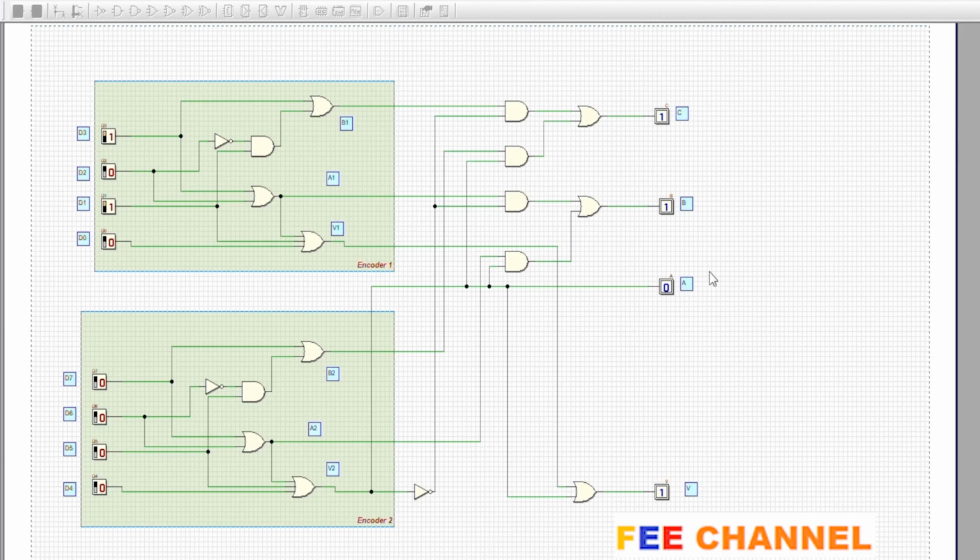But you can also use some directly available encoder ICs. For example, this IC 74148 is also an 8-to-3 priority encoder. And it can be directly used for some applications. But this IC has active low inputs and outputs. So while using this IC, you need to keep that in mind. If required, I will also make a separate video on this IC. But right now, I am including the datasheet of the same IC in the description. So for more information you can check that link.